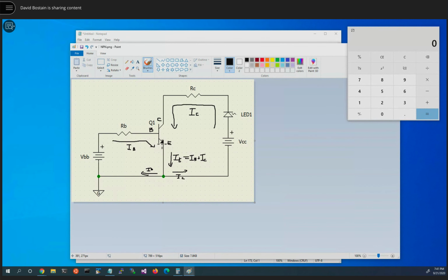Now the transistor, we want to operate as a switch. That means that this current times beta must be larger than this current. If it was exactly the same, we'd be operating like an amplifier. We want it to be larger, so this current cannot reach that value, limited by this resistor, of course, so that we're literally switching it full on or full off. We need to have beta. If I don't give you a value for beta, assume the number 100. Write that down. That's on the test.